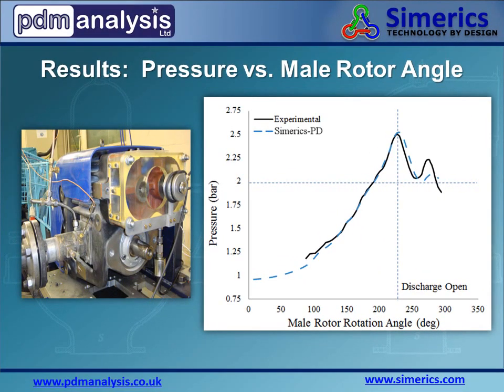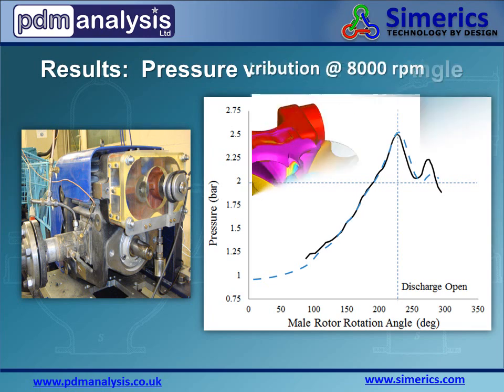This chart shows how Simerics-PD was able to capture the pressure magnitude throughout the rotational cycle of the male rotor. Specifically of interest were the results at the 230-degree position where the discharge was fully open.